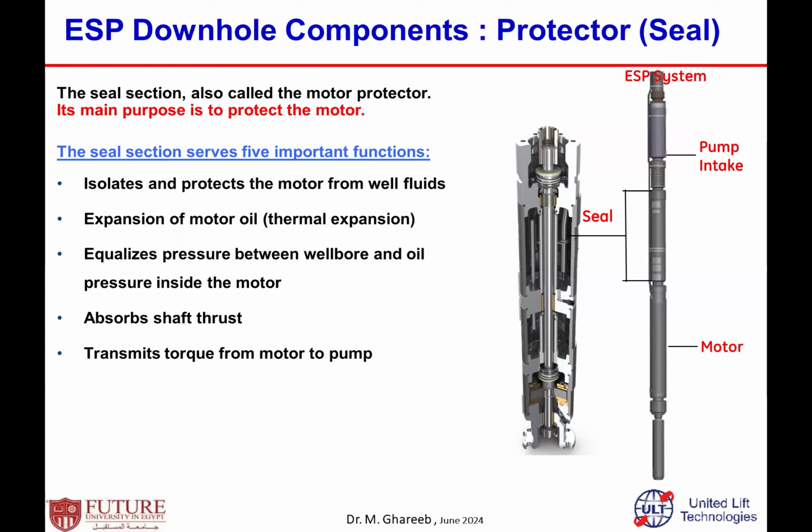Second, since this is an electric motor, there is oil inside, used for insulation, cooling, and a lot of other things for the motor. This oil is in enclosed cylinders, and the oil temperature can change, and the motor itself generates heat. Then this oil can expand. If the oil expands in a closed section, what will happen? It generates higher pressure, which can damage the motor.